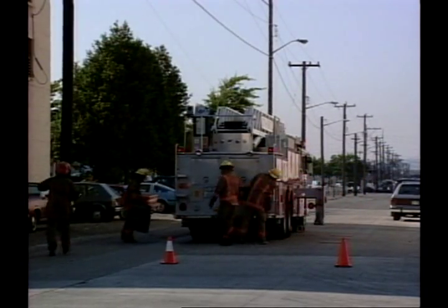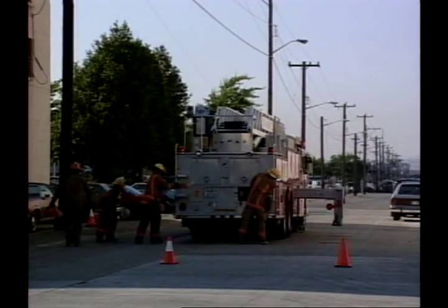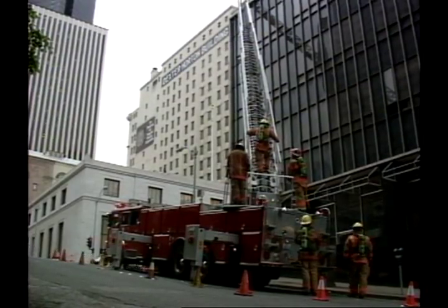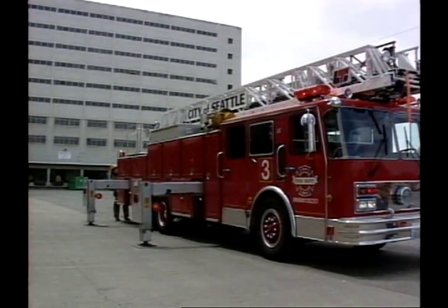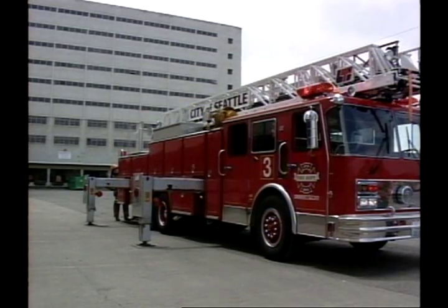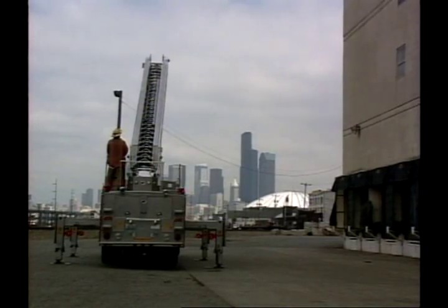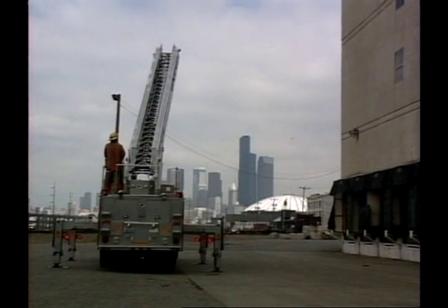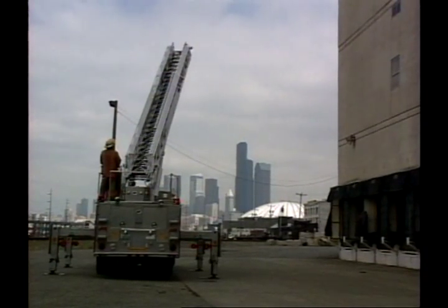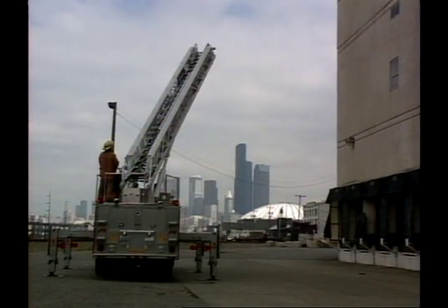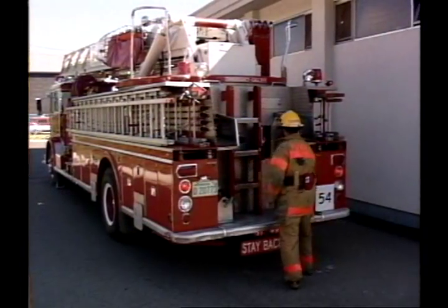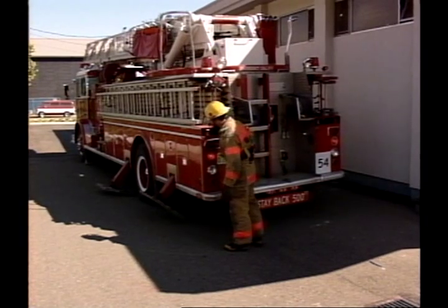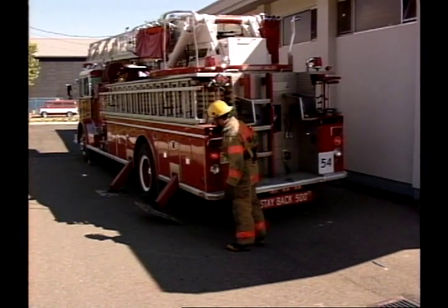Let's look at some general principles for stabilizing on both even and uneven terrain. Ideally, you will be stabilizing the apparatus on even terrain. Flat terrain allows for the greatest stability and also the maximum range of safe movement of the aerial device. Generally, there will be one control for each stabilizer. In most cases, you can operate more than one control at a time.